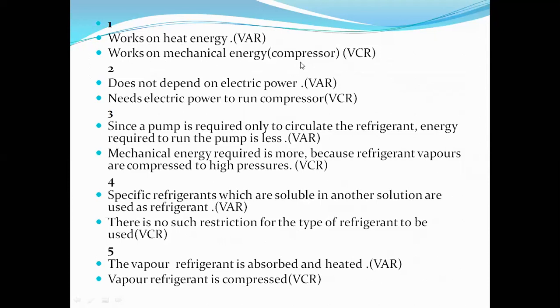Mechanical energy means we have a compressor. Compressor does not exist in VAR, so rather it utilizes heat energy. As I said, we have a generator, and the generator does not exist in VCR. So the first difference is VAR works on heat energy, whereas VCR works on mechanical energy. Second difference is that it does not depend upon electric power.